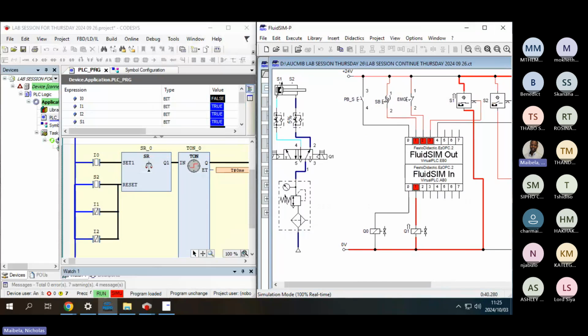So before the counter stops counting, if you press the stop button with this connection that we have modified, your advancement will not start, right? But we are doing this so that we can have complete control over the system, right? So it's always a must. It's always important that you have stop buttons, right? If you don't have stop buttons, you won't be in control of your process, right?